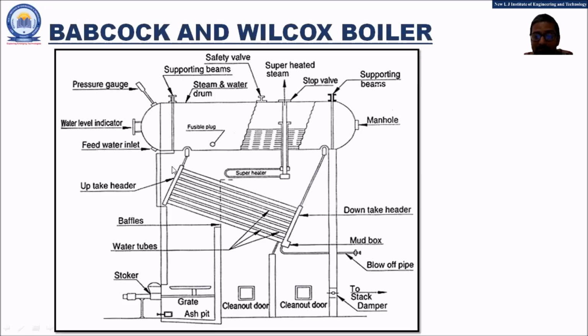These hot gases will be moving in a sinusoidal pattern. You can see the cursor of my pointer. I am showing you the sinusoidal pattern of the path of the flue gases. It is already mentioned in your textbook by the arrows. If you can observe, it is a sinusoidal pattern. This pattern is developed by the introduction of the baffles which are given in the construction. So the baffles are provided, resulting in the sinusoidal pattern of the hot gases.